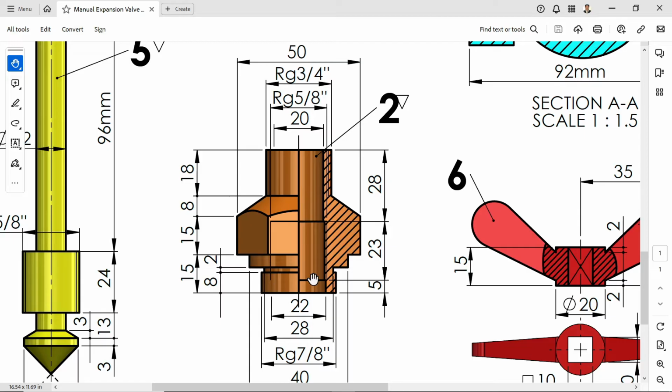Now here let's make the internal holes. See, in top side 28 depth and the diameter 20. From bottom there is a small hole 22 diameter, depth 5, and at center there is a, and if you just zoom, go upside, and you will see this is 5 by 8 inch. And this one we considered for the diameter 22.99, or even though let's say 23.